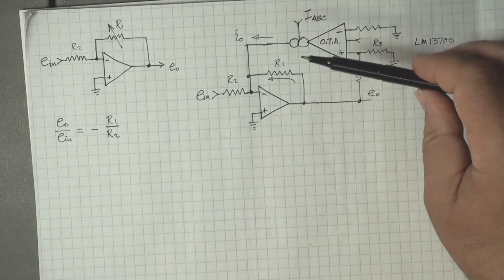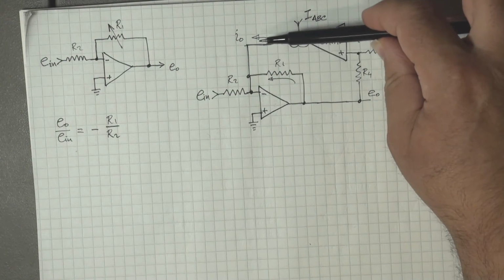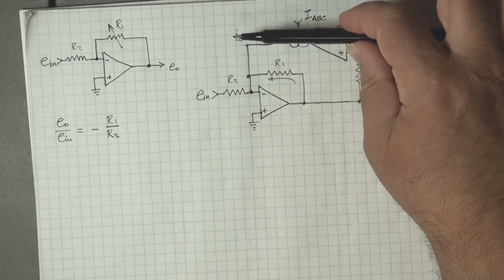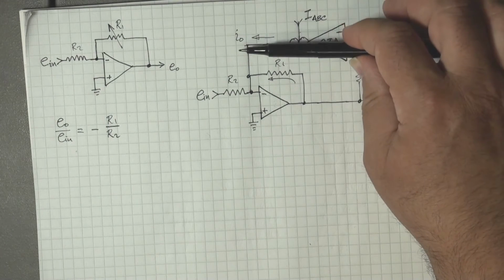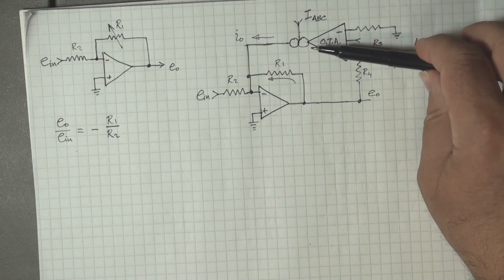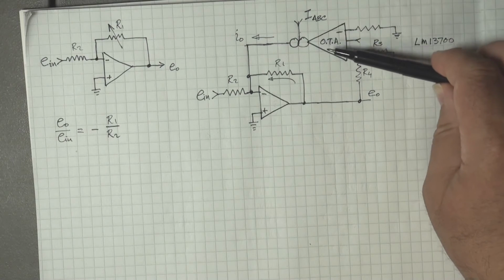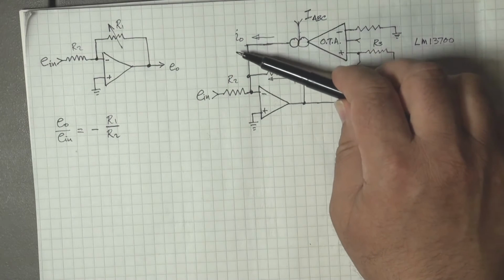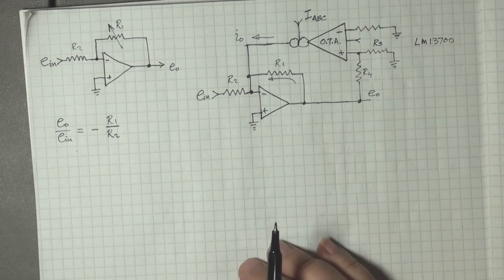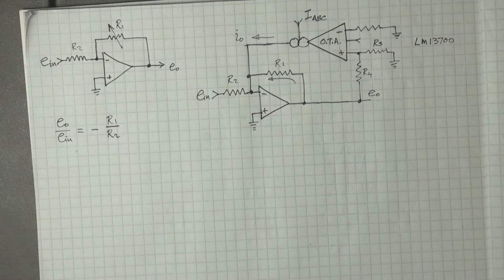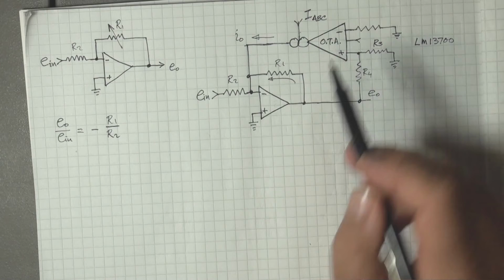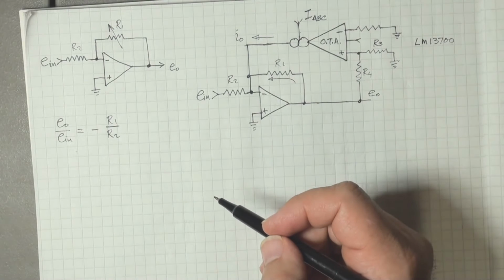So from the point of view of the op-amp, this OTA appears as a voltage or current controlled resistor, where you increase the input current, the resistance is going down because the output current is increasing. So this is in effect how to control the gain of the op-amp through the use of an OTA, an Operational Transconductance Amplifier.